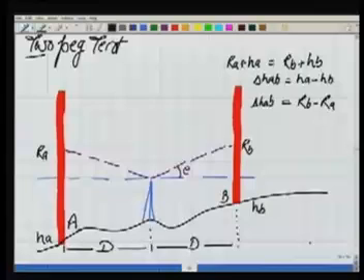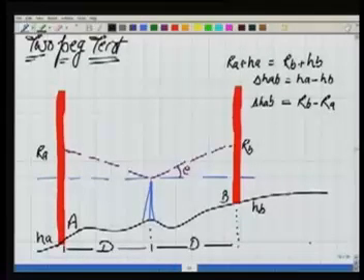The field is very different. So in that case, it will be desirable that we eliminate this problem from the instrument itself, and this is called permanent adjustment. So we'll try to see how we can adjust our instrument, and before that, to test if these two are parallel or not, we'll carry out a test which is called the two-peg test.